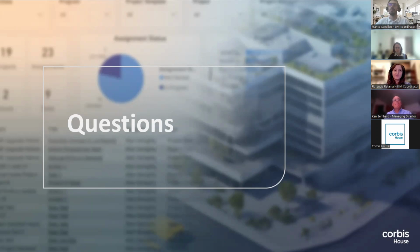Yeah, as I said previously, this report allows you to connect with different platforms such as Procore or Autodesk Construction Cloud, and these platforms provide different plugins that can connect the Navisworks model with the platform. So we can associate a specific clash or a group of clashes with an RFI, and this information is directly connected with our report. So we can track this information using a comment or directly the RFI number.